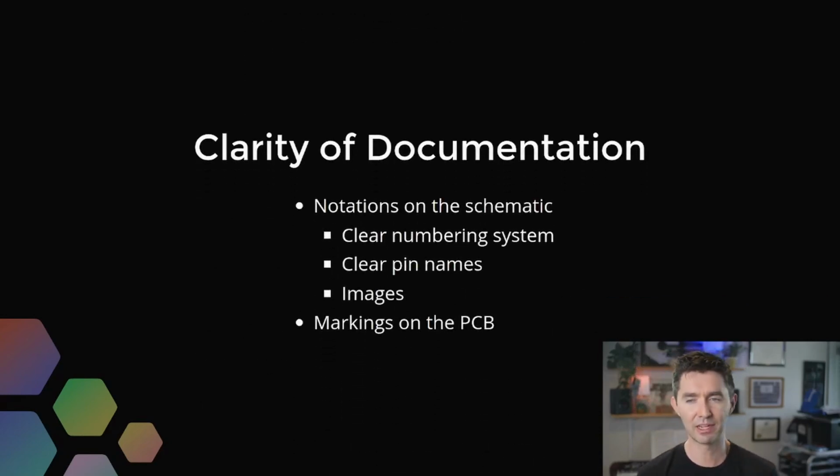And finally, clarity of documentation. I think it's really important to have stuff on the schematic, a clear numbering system, clear pin names, standardized pin names, things that make sense, so that if you're looking at it, you should be able to read a pin name and it's not ambiguous.